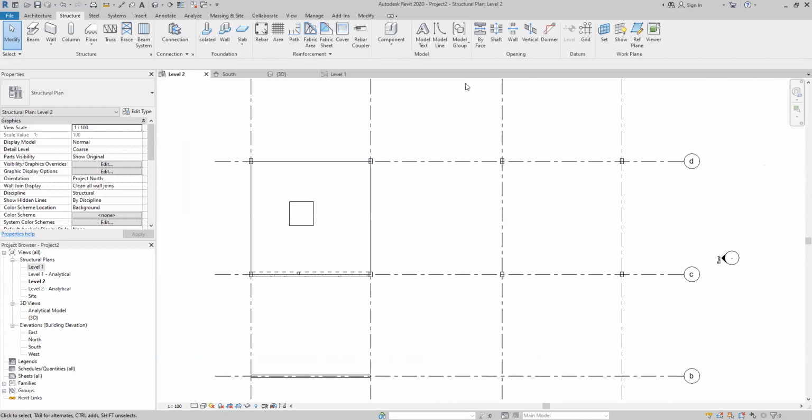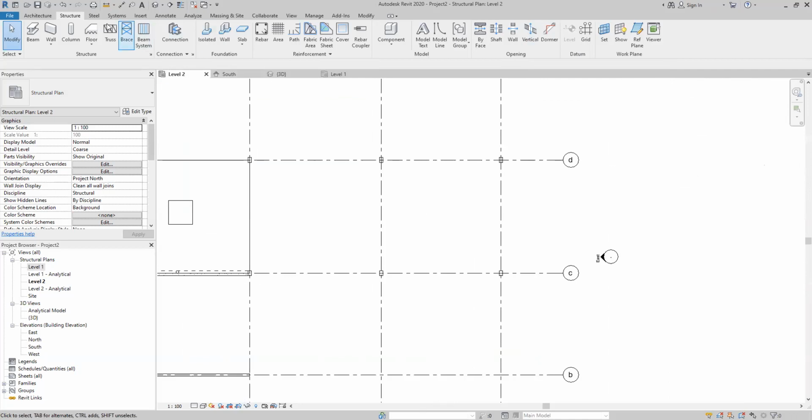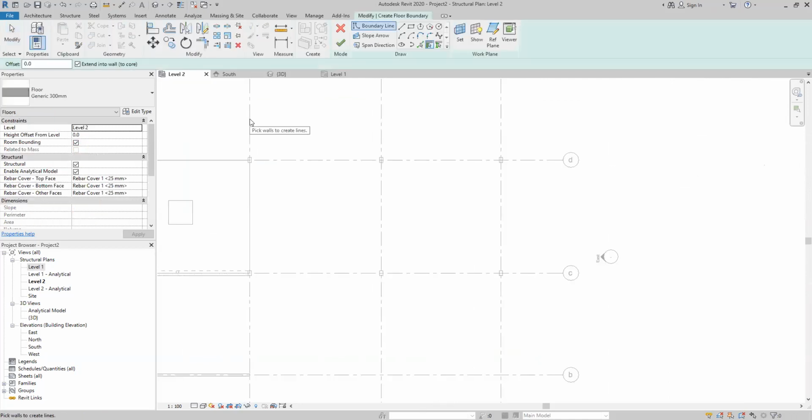Okay. Now let's see what a vertical opening is. So this vertical opening we normally use for the ramp, right? So let me draw the ramp first. Last week we saw how to draw the ramp. So ramp is also like a slab. So what we want to do is draw the rectangular slab. So I draw the rectangular slab first, right? Then I have to draw the arrow. Okay, from which level to which level it is going. So I pick the arrow from bottom to top.